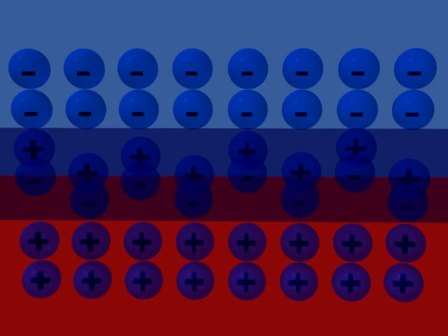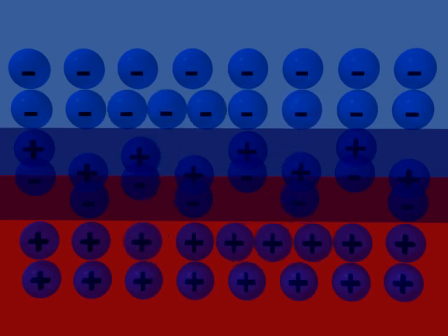the other layer. However, if photons hit the silicon layers, electron-hole pairs will be created. If this happens in the electrical field, electrons are moved to the N-doped layer and holes are moved to the P-doped layer. The system will fall into a state of imbalance because of an excess of electrons in the N-doped layer. The corresponding holes can be found in the P-doped layer.